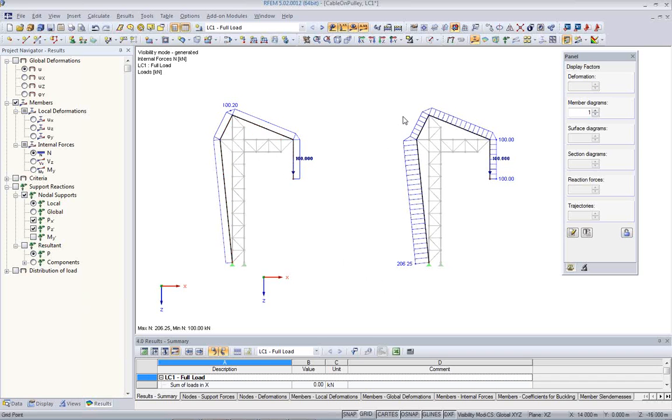And on the right side we see the difference. There's 100 kilonewton here, which is pretty okay. But here we have 200 kilonewton, which is introduced due to the bending of the entire structure, and here there's an additional axial force in that cable. So if you don't have the ability to analyze such a model, you'll get totally wrong forces in your cables if you use regular cables.